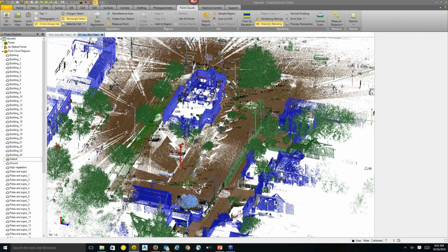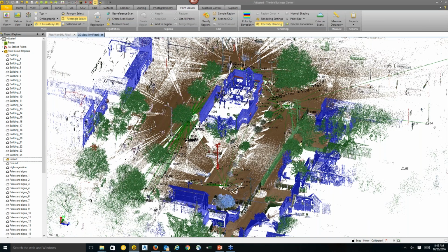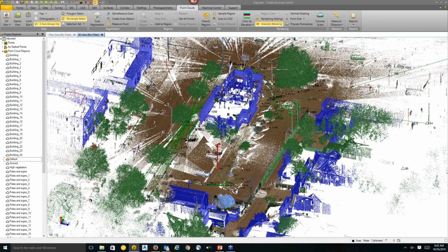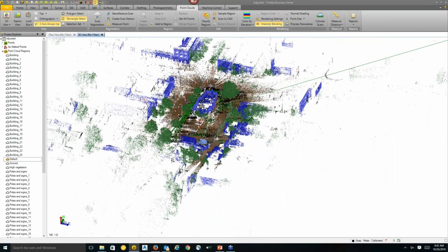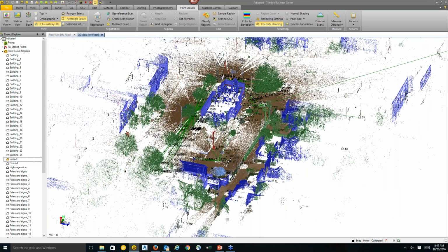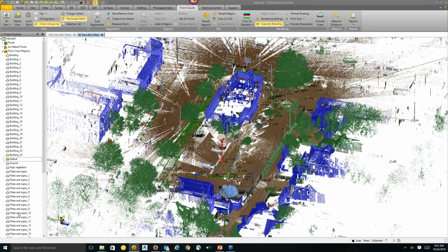It's my habit. I like to work with JXLs, and I strongly recommend all of you that are still using DC files to start using JXL more. So every time before I leave the field, I will export fixed formats in Trimble Access and always use JXL. It just gives you a lot more traceability. If something goes wrong with the job file, it's hard to tell because it's a binary file.